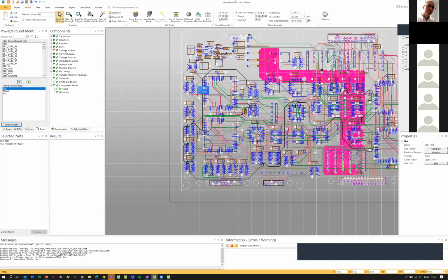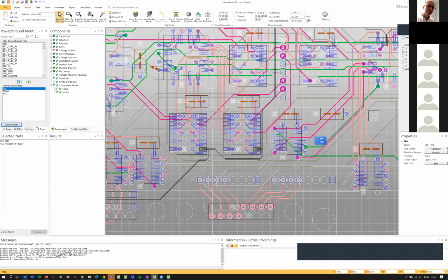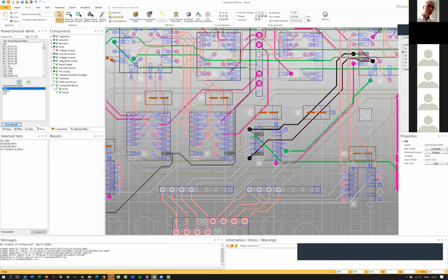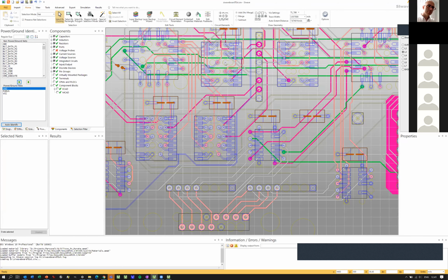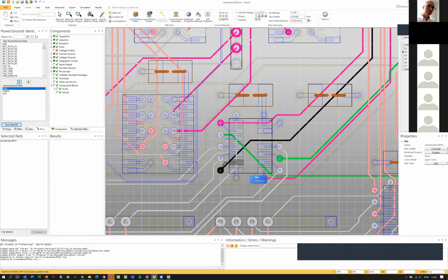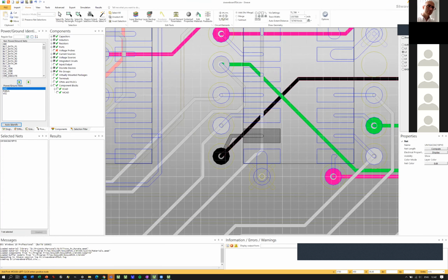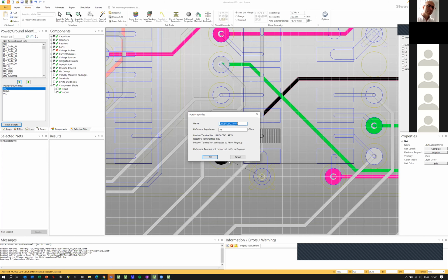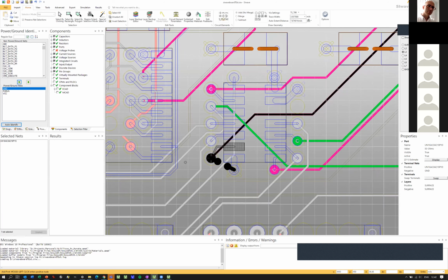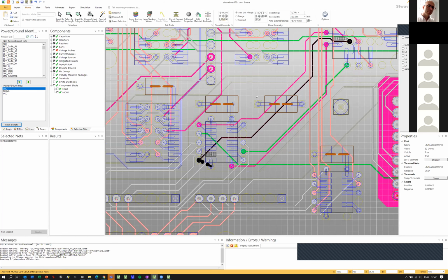Okay, so maybe this next one. Yeah. I will unselect everything and take, this is a bit longer. Yeah, okay, this one. Actually, I have no idea what this signal is, but I don't care. Now this is the demo, so I will click a port here, and is this ground? Yes. So this unknown net to ground. There's one port, 50 ohms, yes. And I add the second port on the other side.